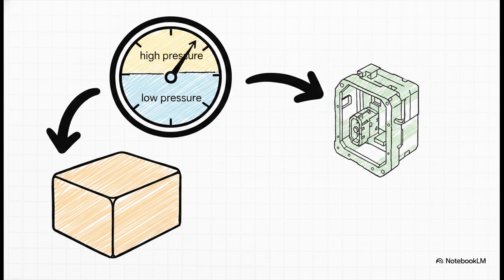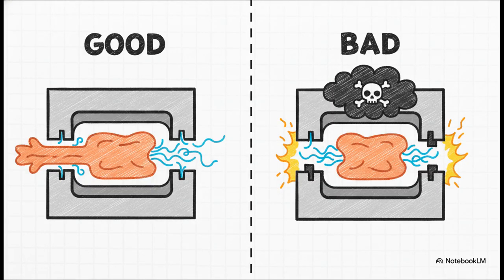That way you pack the mold fully while minimizing the residual internal stresses that inevitably lead to warpage down the line. Okay, this next part is absolutely crucial: getting the trapped air out of the mold cavity as that plastic rushes in. Your mold needs vent depths of 0.025 to 0.05 millimeters, placed strategically right at the last fill areas. And guys, this isn't just about avoiding cosmetic burn marks or short shots.